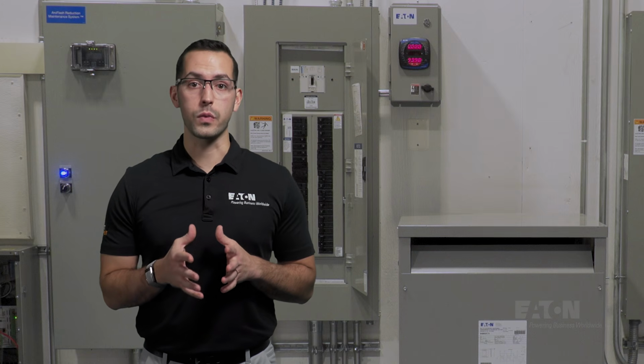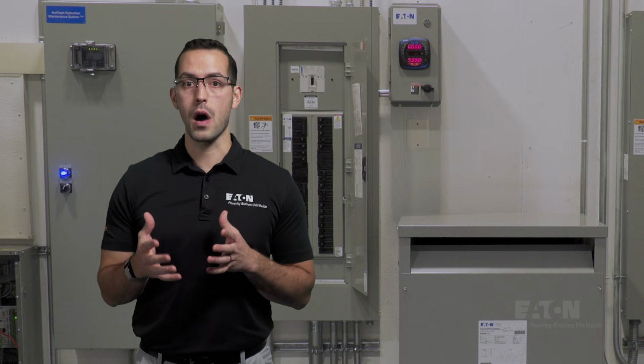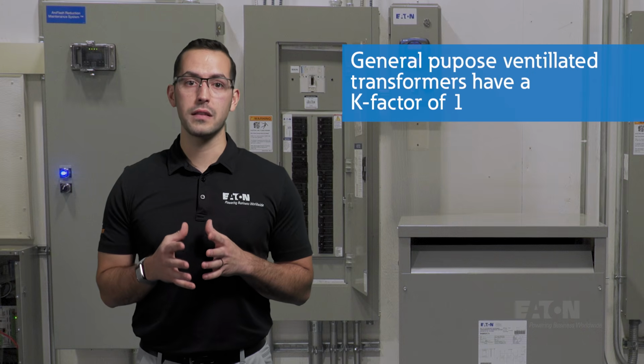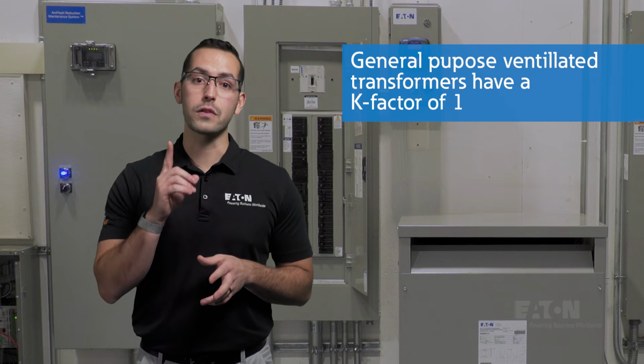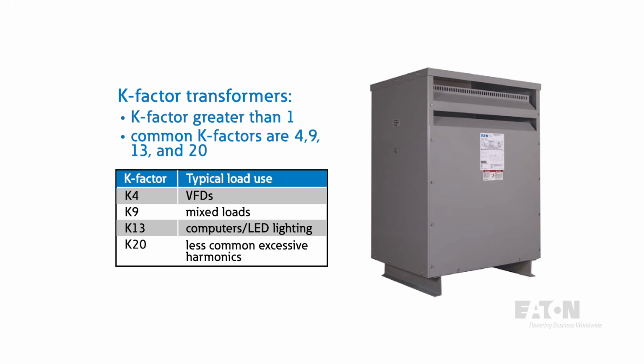Transformers may carry a K-factor rating to define the transformer's ability to withstand the additional heating generated by harmonic currents. The general-purpose ventilated transformers described earlier have a K-factor of 1 for general-purpose linear loads. Typically, a transformer is not called a K-factor transformer unless it has a K-factor greater than 1. Common K-factors are 4, 9, 13, and 20. K-factor transformers are typically oversized versus general-purpose transformers and have other differentiating design characteristics, such as 200% neutrals, electrostatic shields, and core designs to reduce induction levels.